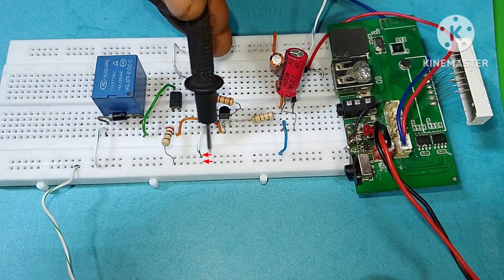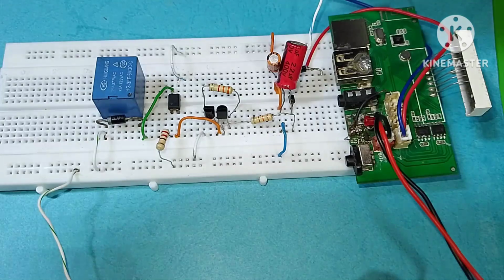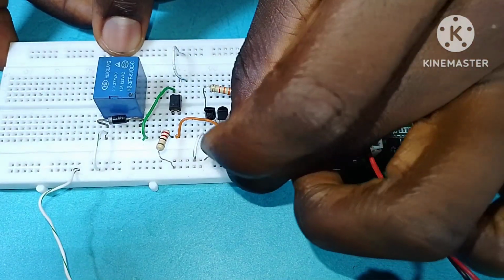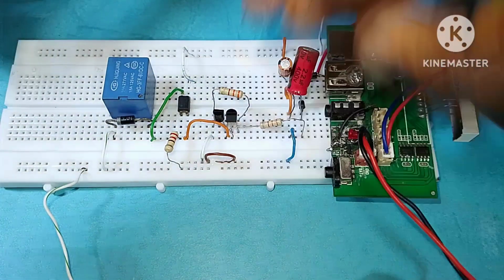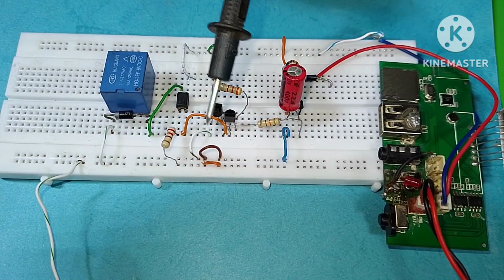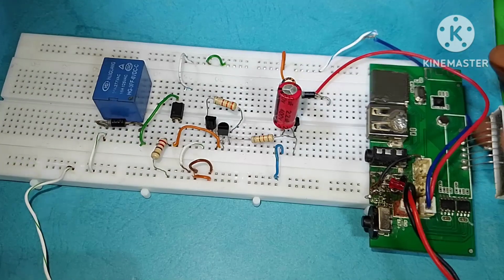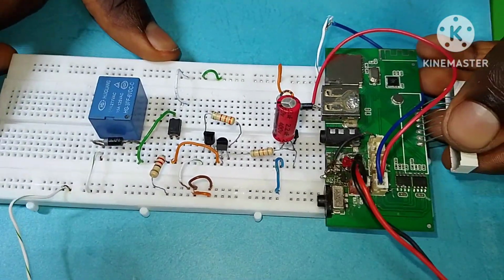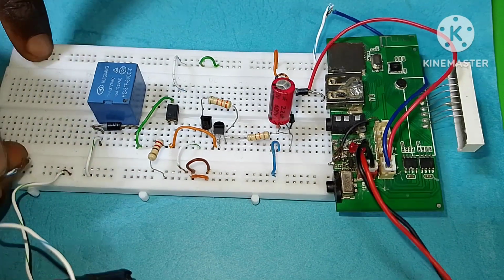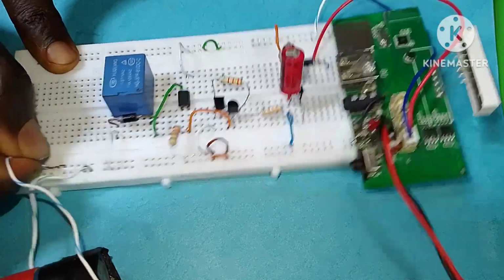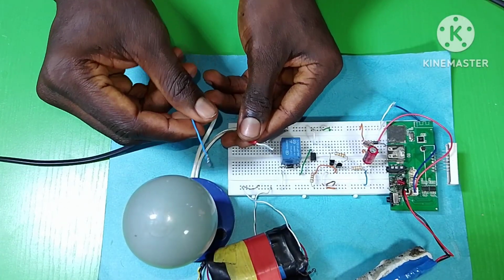And next, remember to connect these two points, because we have no connection between these two points. So I'm going to be adding jumper wires so that they can have connection with each other. And don't forget, you're going to do it for all sides, both up and down, like what I've done right now. You can see they are all connected. So I think now we are done with these circuits. The last thing we're going to do now is connect our negative supply to the ground, and then that is done, and we are going to be powering this.